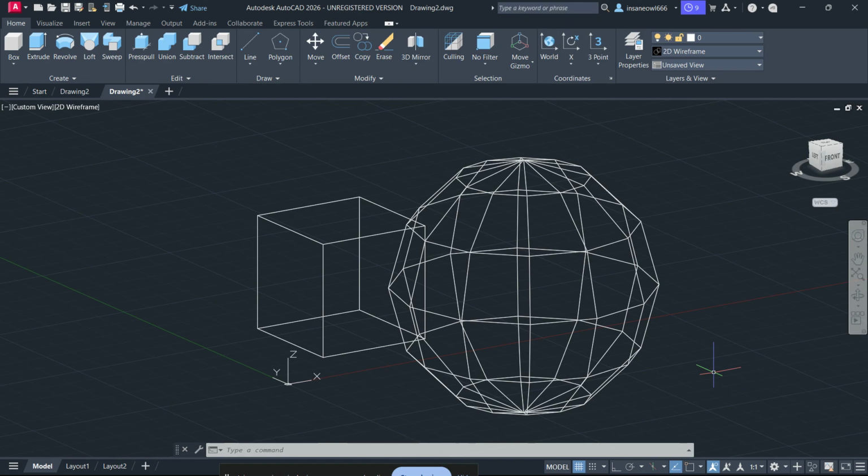First, let's understand what error 97022 really means. It usually appears when Autodesk ShapeManager cannot resolve a face-to-face or face-to-edge intersection. That means two objects may look fine on screen, but internally the software cannot decide how the solids should combine. This is very common when faces are nearly coincident, when a model has non-manifold topology, or when one object is self-intersecting. In simpler terms, the geometry may be too messy for the Boolean operation to finish. Now let's go through the fixes in the best order.